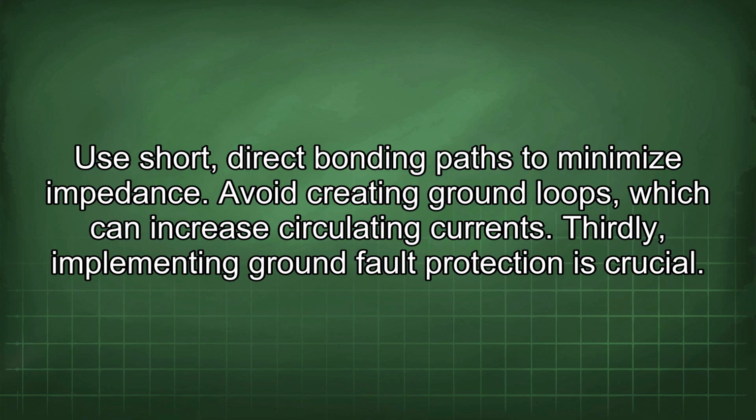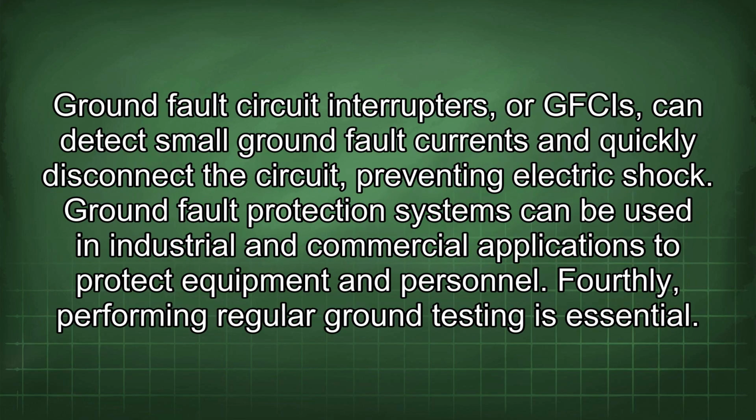Thirdly, implementing ground fault protection is crucial. Ground fault circuit interrupters, or GFCIs, can detect small ground fault currents and quickly disconnect the circuit, preventing electric shock. Ground fault protection systems can be used in industrial and commercial applications to protect equipment and personnel.